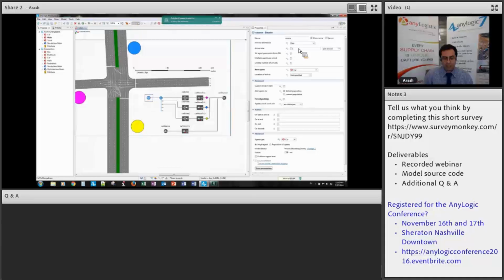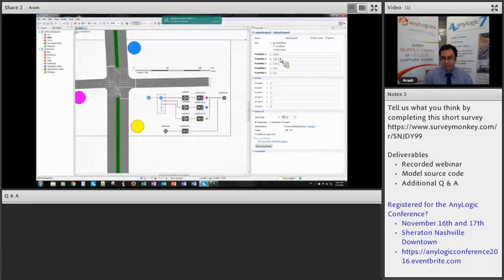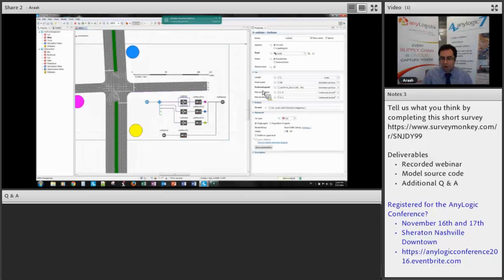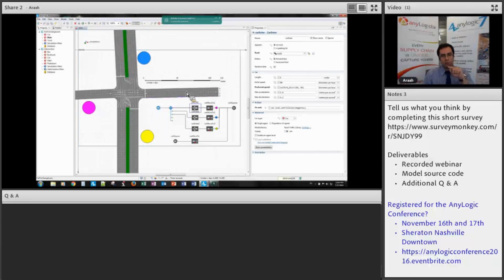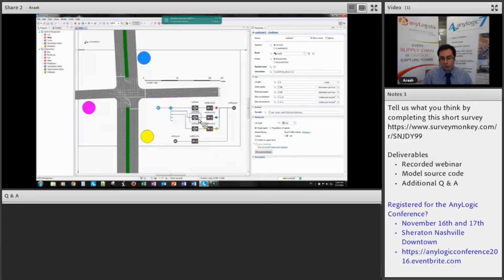And then we have these select output 5 blocks that let us separate them into different groups. And here on enter car, I will put them on a specific place. For example, for the cars that are passing through and they want to go straight, I assign a random lane to them. But for the cars that are turning right, I say that they should be either in the 0 or 1 lane. So they will be on the right side of the road.